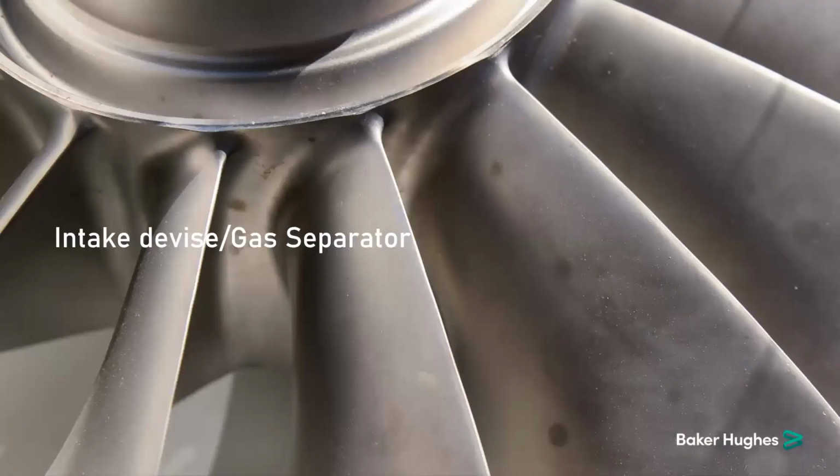With that, we close the pump section, and I will quickly recap the ESP pump component. The ESP pump consists of the impeller, diffuser, shaft, and housing. Each impeller is connected with its diffuser inside the housing, connected from the top with the discharge head and from the bottom with the intake or another pump section. Impellers and diffusers have 3 categories in terms of hydraulic design: radial, axial, and mixed. Radial is a 90-degree path for the flow, while mixed is almost 45-degree.